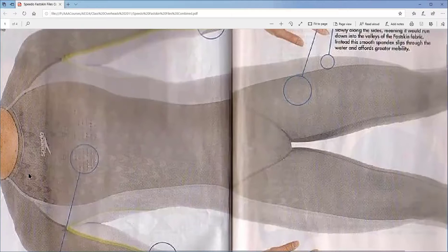All right, the first thing to notice is right here. Is it clear enough? You can see these triangle-shaped patterns on this part of the suit. This is based after what they see in shark skins. The shark skin has little triangle-shaped patterns, and they've discovered that these patterns create eddies in the flow that reduce the drag. They prevent separation over the chest. So this reduces drag here as the flow comes over the top. Essentially think of the chest as the top of the airfoil.